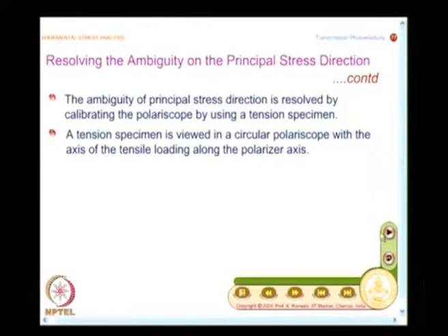And what is going to happen is the retardation introduced will be so small, I would not have a full fringe order come and occupy this. If I know the color code and the color sequence, it is possible for me to assess whether the fringe order has increased or decreased by a particular rotation of the analyzer. So, the calibration is looked at from that point of view.